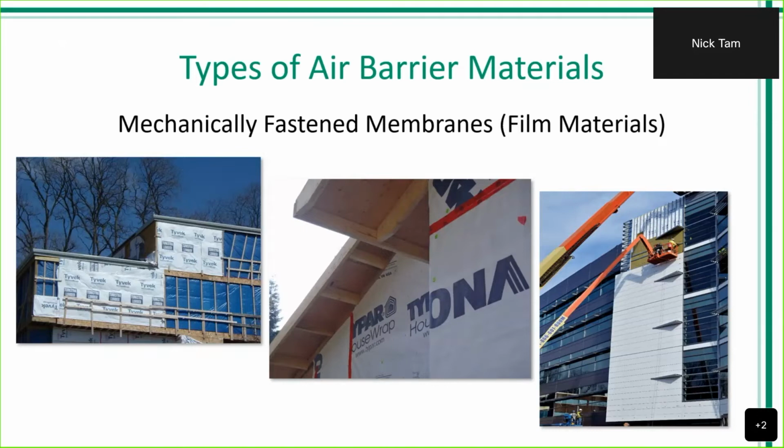Also note with materials like this that I mentioned wind pressure earlier. Well, if we're in a project in West Texas where it's continuously windy, there is a potential that this material can be lifted up a little bit with more ease and it can become damaged. And with that, we're going to have replacement costs, and it's going to be a little bit of a scheduling issue as well.